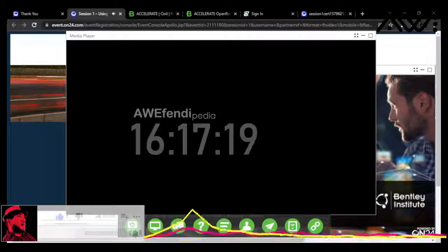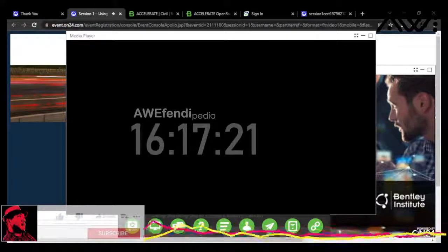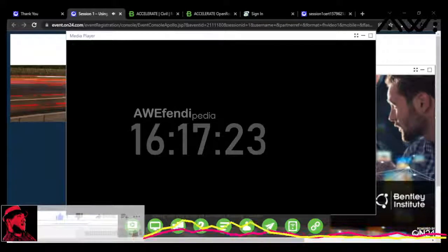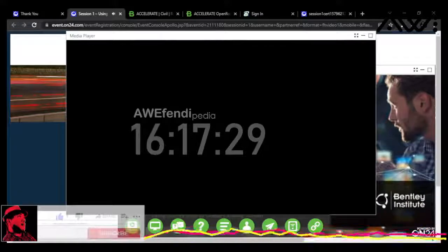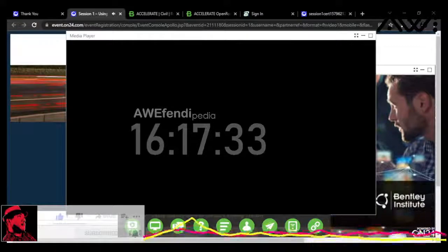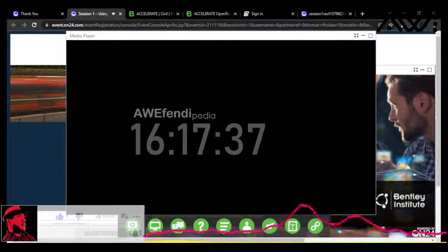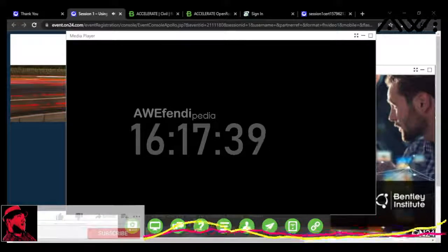And we have those same override errors where we're doing those check shots on the traverse points. All of them match up pretty good. They're all the TP codes, so we're just going to say overwrite and apply all on that. Okay, so we're going to bring in the next 6 files there. This is 12 through the end, and it's going to generate all the codes on that.